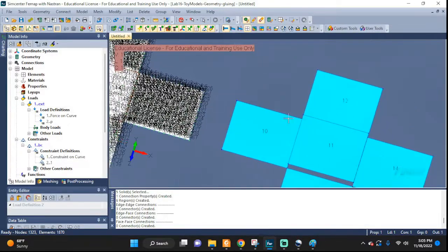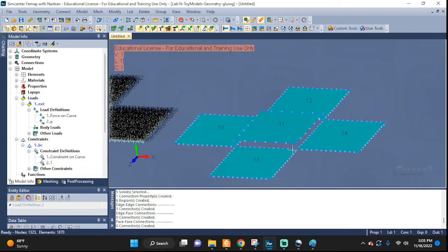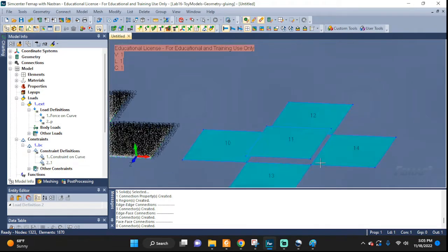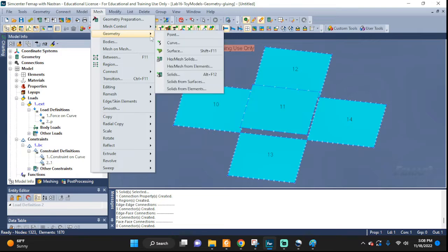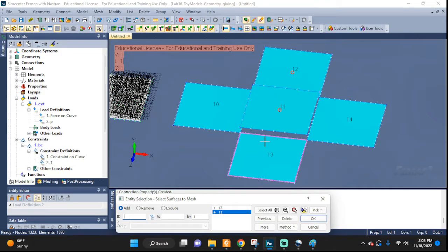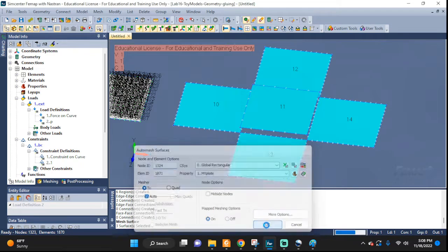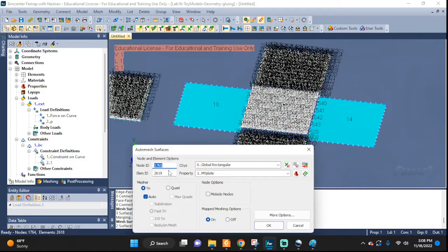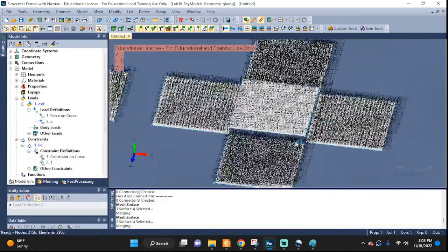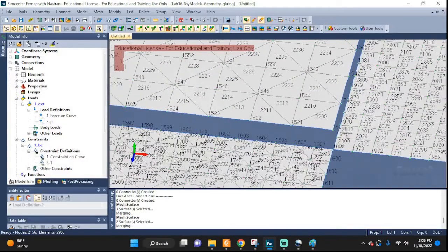Let's go to the last one. Now here we have a massive gap, right? We're gonna have to make sure we specify to the software that, hey, include this massive gap in it. Here, let's apply the same meshing. Again, surfaces, I'm gonna mesh this and this the same, leave those like that, and I'm gonna mesh geometry, surface, this and this. Okay, I'm gonna do this with the quads. Okay, and for obvious reasons, not just are the meshes unaligned, we also have a huge gap.